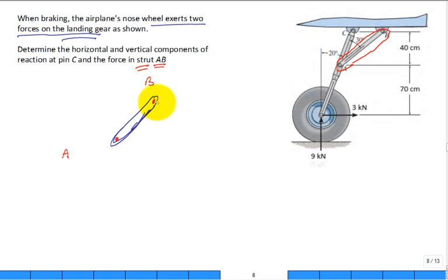You could then draw the free body diagram. A lot of students would say, I don't know the direction, so I'm going to assume positive BX and positive BY, and positive AX and positive AY. That's true, you could do that. And then you'd say there are 4 unknowns.